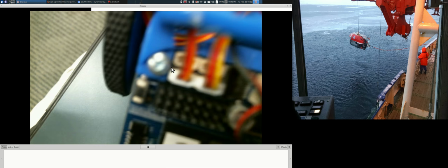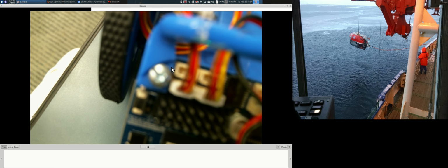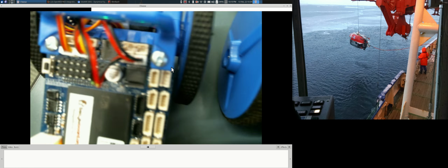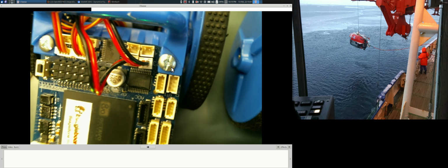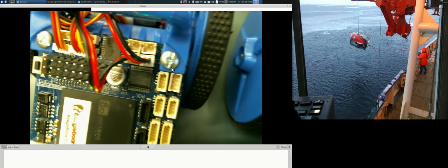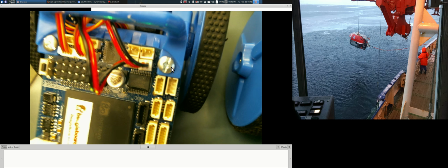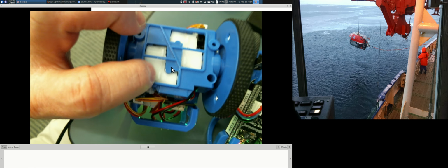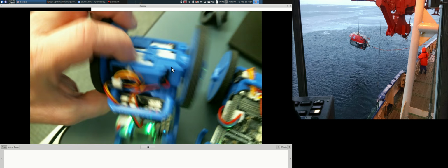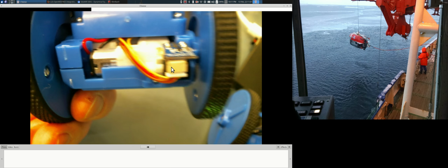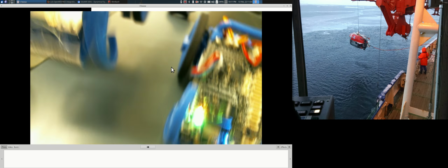The encoder connections have 4 pins for power, ground, channel 1 and channel 2. And these are the servo output pins, and so these do PWM output at the battery pack voltage level, so they'll drive motors directly. They've got a plus and a minus, and there's 4 of them. That's what's driving the servos on the EduMIP. The motors are inside here with a gearbox. And here's a motor. You can see a motor there, a gearbox, and then the encoder off to the right.